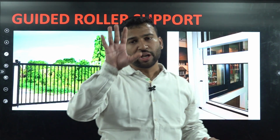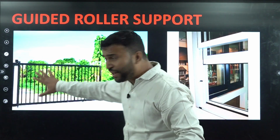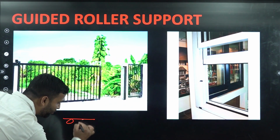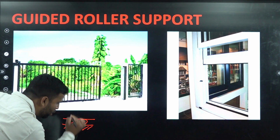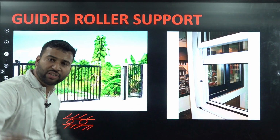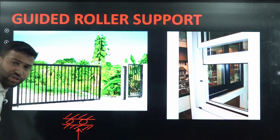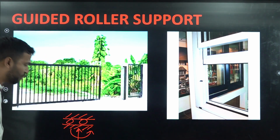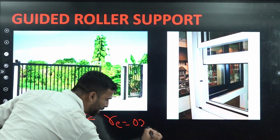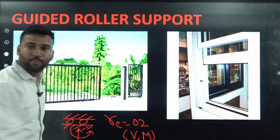So sir, on a guided roller how many reactions are possible? If we are talking about the horizontal guided roller, which will appear like this in our structure, horizontal movement is allowed, so horizontal reaction will not exist here, but vertical reaction will exist as well as moment of resistance will exist here. So in case of horizontal guided roller, we will have two reactions. The first one is vertical reaction and the second one is moment.